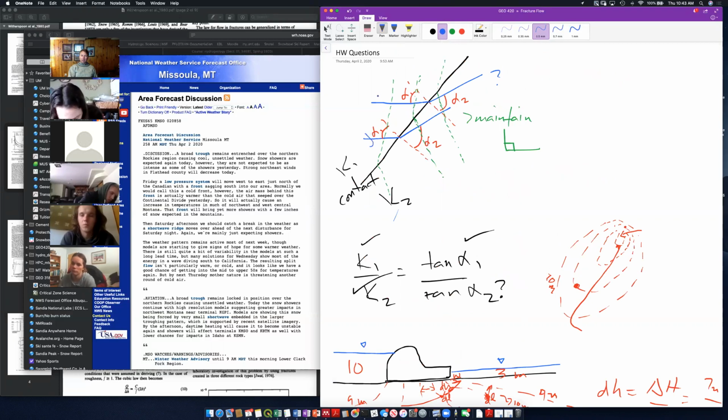Here are my incoming flow paths. You've been given, or you can measure, these incident angles. Then you've got to calculate and draw the resulting angles as it moves into that high hydraulic conductivity material. And you've got to tell me whether the flow path refraction would result in the wells being contaminated or not.